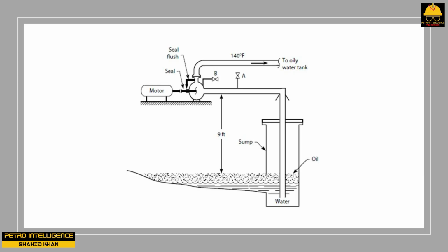The problem with priming the pump shown in the picture is that the water needed to fill the pump's case, that is, to prime the pump, is below the pump itself. Certainly, there are self-priming pumps. These pumps are designed to compress very, very small volumes of air, and to produce very, very small discharge pressures with the air. The circulation pump on my swimming pool is of this type. After running 15 minutes or so, it draws through itself a few cubic feet of air before it can pick up suction. Most high-head, large-volume pumps must be primed with an external source of water.